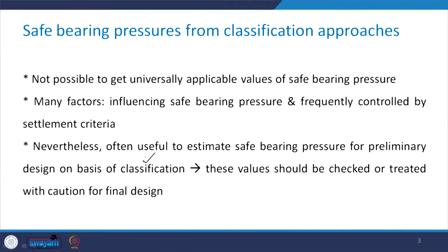Nevertheless, these approaches are often useful to estimate the safe bearing pressure for preliminary design on the basis of classification, but we need to be careful that the values we get from the classification approaches should be checked or treated with caution for the final design. For preliminary design one can use these values, but for the final design one needs to be extremely careful.